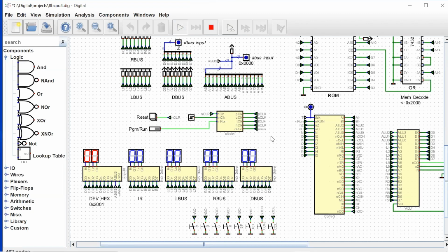So our simulation's going. The first thing you can see is our clock signals are not right. This doesn't start up in a valid state, so we need to do a reset first thing. Okay, now we can see that our clock signals look to be right. We're at our negative clock, which is our starting state, and here we're at instruction step tick 0. We can see a little tick display here.